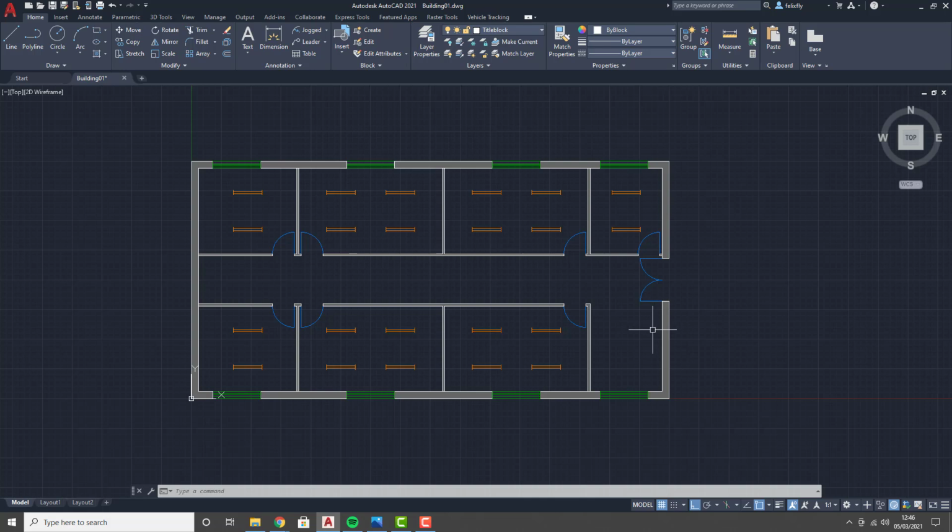So we draw this at 20 meters wide, the way it wants to be. And then what we do, we have everything here drawn to actual size, and this is known as our model space. So this is our model of our building, created to actual size in model space. We've got the black background here, and if you look at these tabs, this one says model. So we are in the model space where everything is created actual size as per the real world. We also have these layout tabs. Now, ignore the fact there's 2 of them, okay? We're only going to work with one.